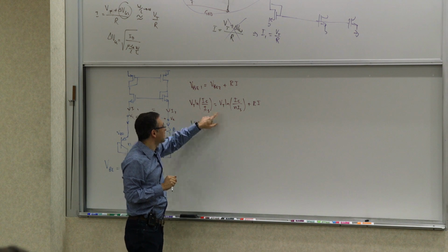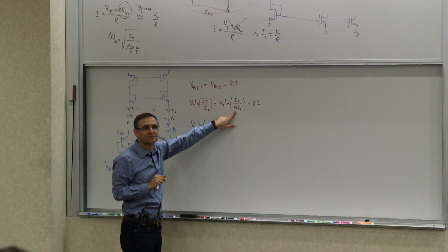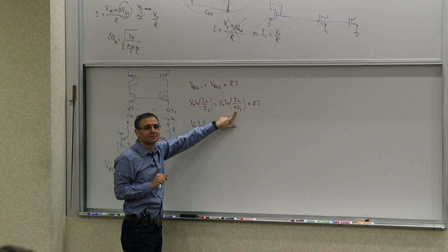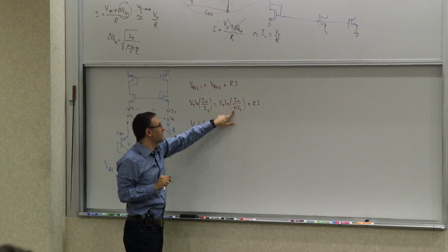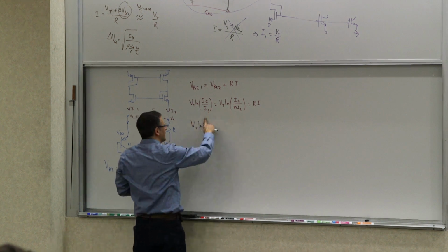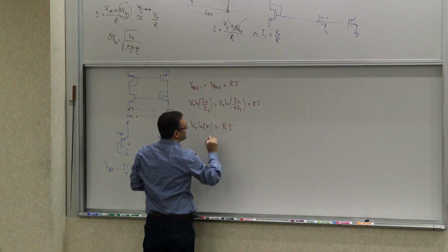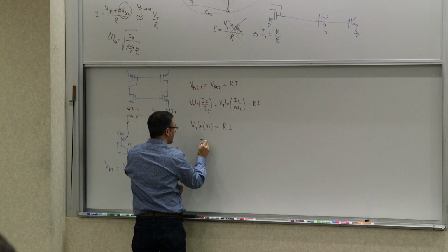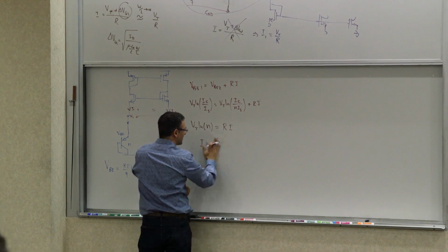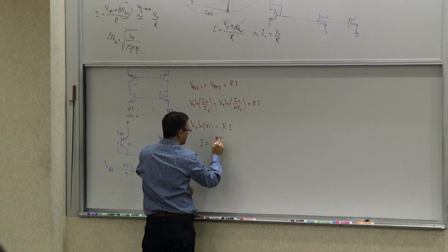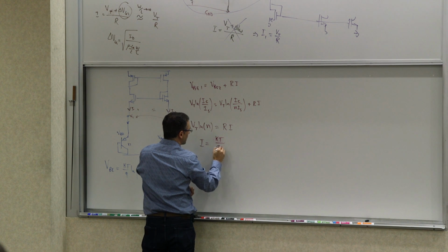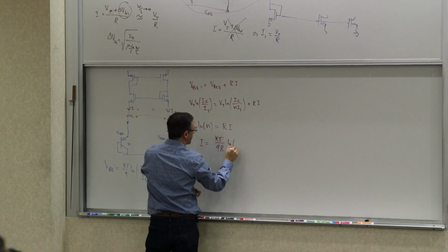What's the ratio of this argument to that argument? What is this divided by that? n, right? Both IC and IS cancel. So I becomes VT, and this VT is really kT over q. Let me just write it as kT over qR natural log of n.